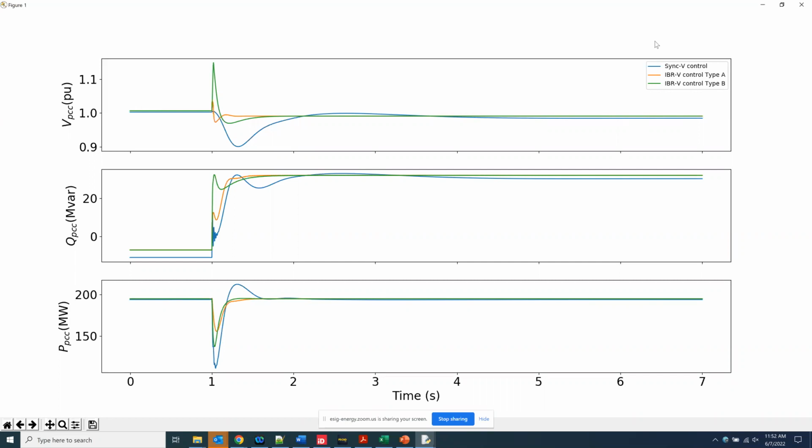Jason, you had a point? I was going to say basically what Nick said, talking about the different aspects and flavors of grid forming services. There are certain cases about what you do to keep the control stable in a weak network, a low SCR network, as opposed to a zero SCR network, a black start, as opposed to providing inertia. All those things are somewhat separate and independent when you look at the control algorithms, but they all have to work together. So the set of services is where you're going: what problem am I trying to solve, and what specific control mechanisms allow us to do that? Exactly, coordinated together.